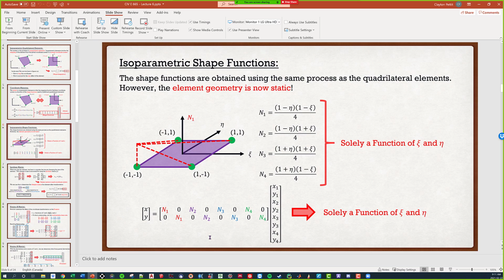This is completely accurate, 100%, which is nice. Remember that if I wanted my x and y coordinates, x1 and x2, all I do is input my shape functions, which are a function of eta. At x1, in terms of the natural coordinate system, it is -1, -1. If I substitute -1, -1 into these shape functions and then multiply by this right here, I'm actually going to get x1 and x2. So it's actually exact when we're dealing with this. Hopefully that answers your question.